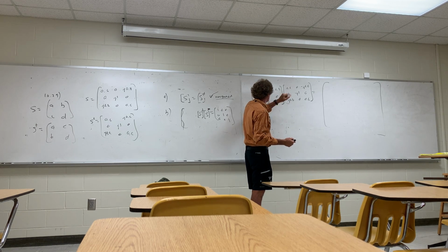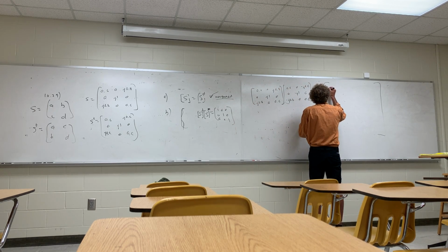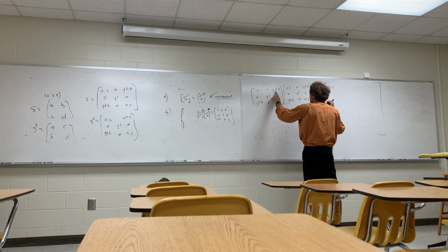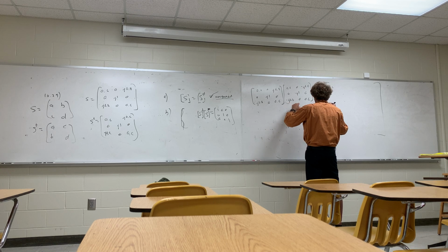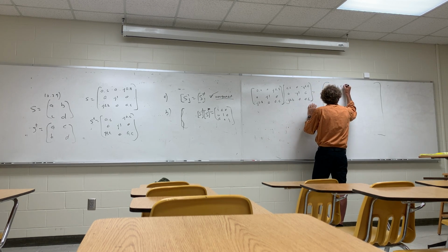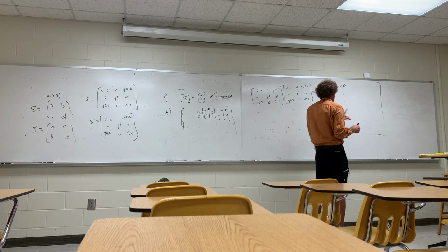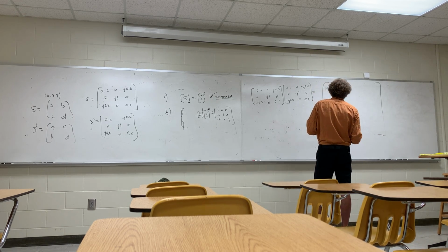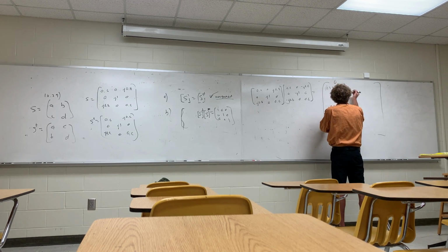So I've got 0.6 times 0.6, and then 0 times 0, and j0.8 times minus j0.8. 0.6 times 0.6 is 0.36, and then 0.8 times 0.8 is 0.64, j times j is minus 1, with the minus it's plus 0.64 here, and that is exactly 1. Whoever made this problem out made it so it's going to turn out that you get the unitary matrix, so it's lossless. So that's 1, this is 1, 1.